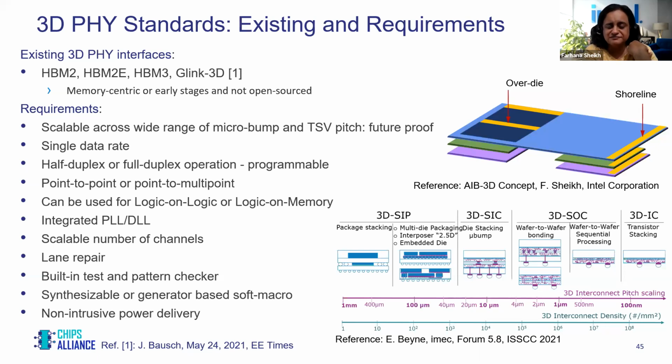Now, obviously, we probably don't need a standard for 3D IC when we're just stacking transistors, but for some of the other types of 3D integration, it's quite possible that a standard would be required if you want to integrate some third-party IP with your own design. We want to be able to allow half duplex or full duplex operation. Half duplex primarily because we do see that, in case somebody wants to integrate a single port memory as on the base die, we want to be able to enable that type of integration.